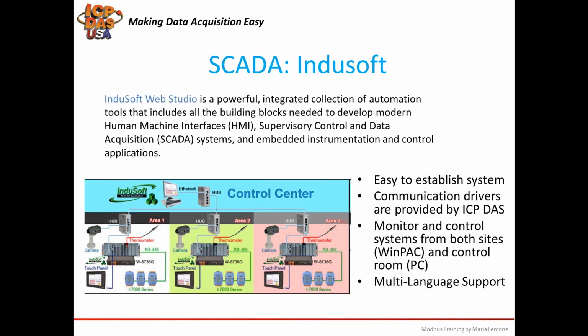SCADA is supervisory control and data acquisition. SCADA software runs on a PC and allows you to interface with various equipment like data acquisition modules, PACs, programmable automation controllers, PLCs, programmable logic controllers, embedded controllers, and instrumentation devices. It comes with a graphics library that you can use to create a visual user interface that represents real applications. They also support scripting, so you can implement some control through some basic programming commands.